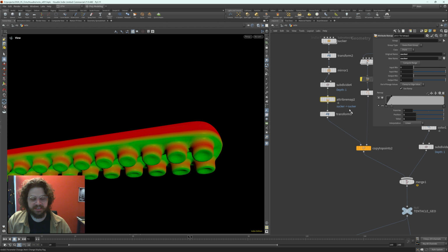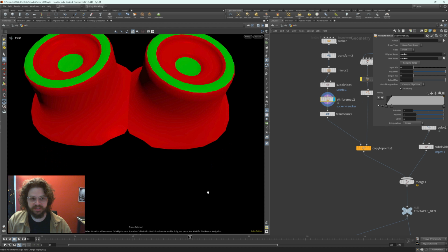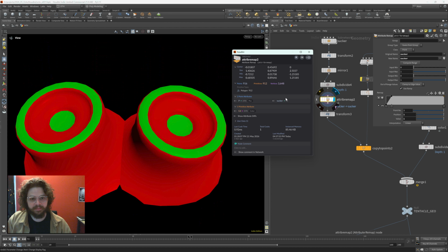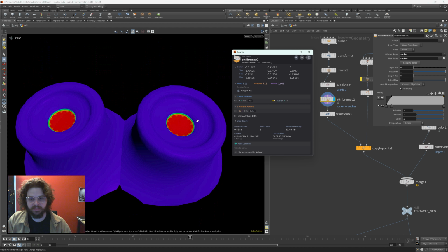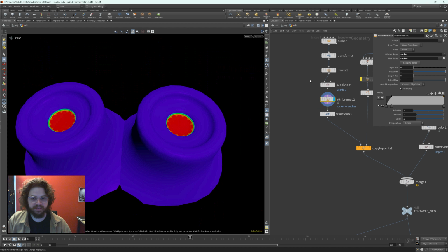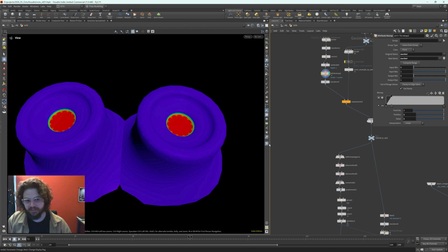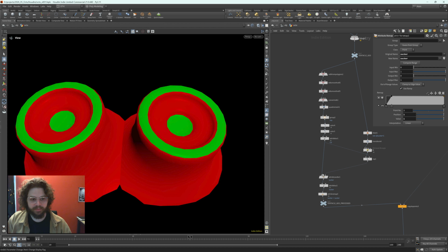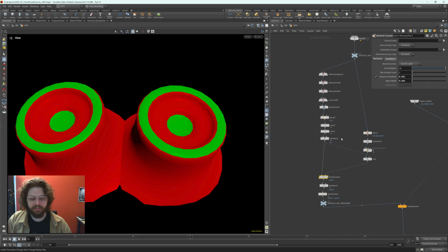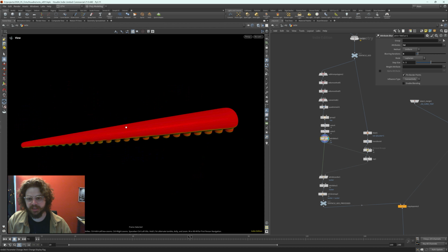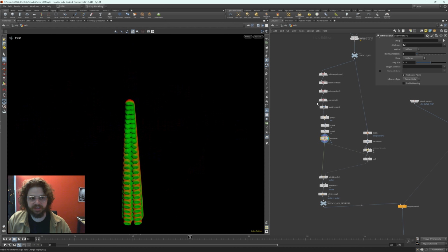Remember back here I said I didn't use this sucker attribute remap thing. I had made this attribute to designate this inner part of the sucker when I did the modeling, but since I ran all of these VDB smoothing operations, my plan was just to attribute transfer that back onto this mesh.